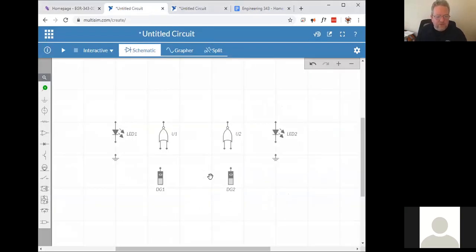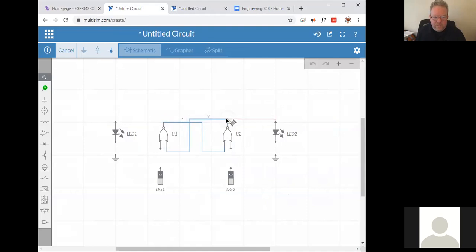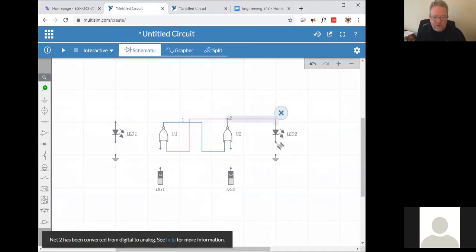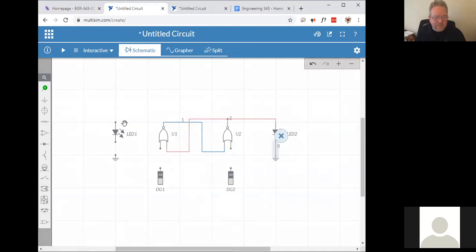All right, so here's the circuit elements that you need to make an RS flip-flop. And as y'all probably have already done here, or at least need to do before Wednesday, you feed the output of this one into this one, you feed the output of this one in over here. Remember that you can kind of move the wires over in Multisim. And you're gonna be monitoring the outputs, and we'll see if we can figure out which one of these outputs is Q or Q prime based on which one lights up.